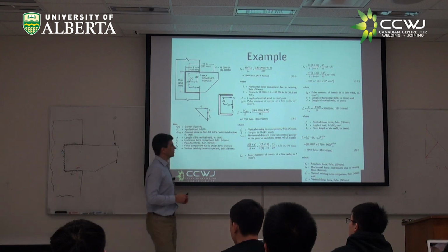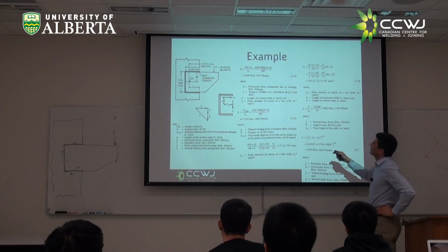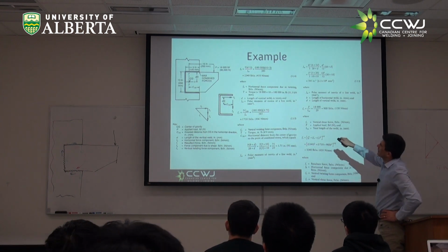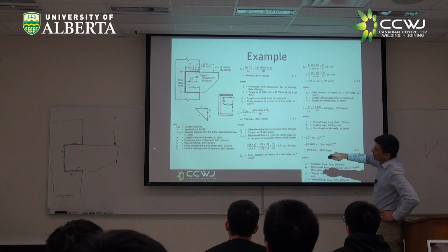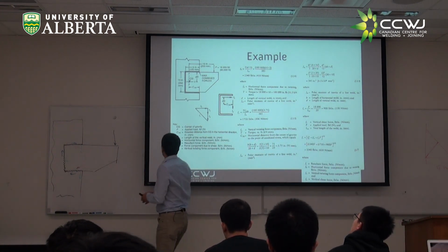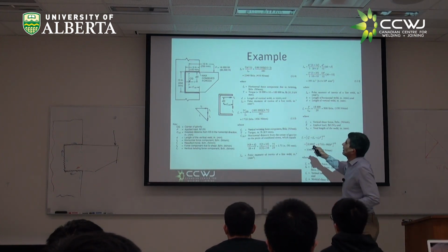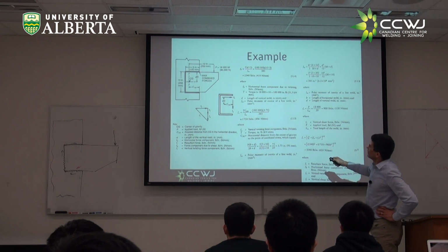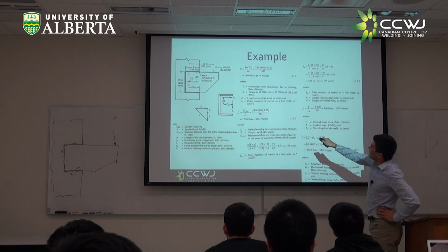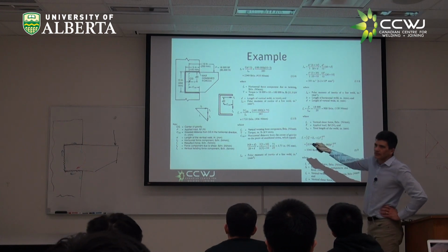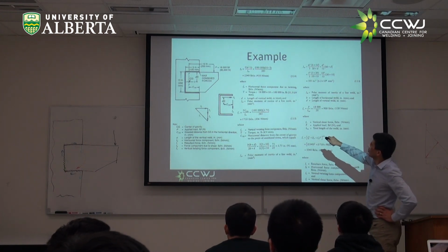Okay, so this is what the guys did. They said, let's calculate the horizontal force, this blue one, from this twisting in here. Let's calculate that force. And that force is the torque, right? They didn't write it all too well, but here you go. Torque is this 18,000 pounds times 10 inches. That's the torque.